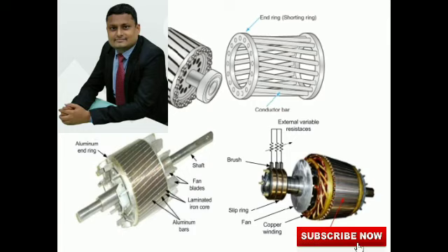Choose the rotor bar, rectangular bar dimension, from the standard table: width, thickness, WSR, and depth, DSR. The rectangular conductor table is given here. You can easily choose these values from the table.